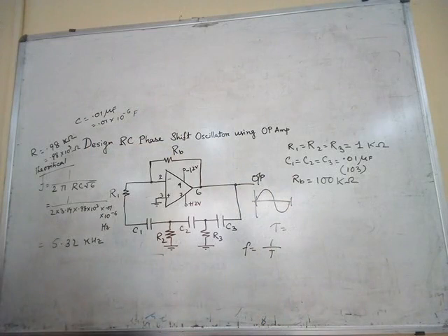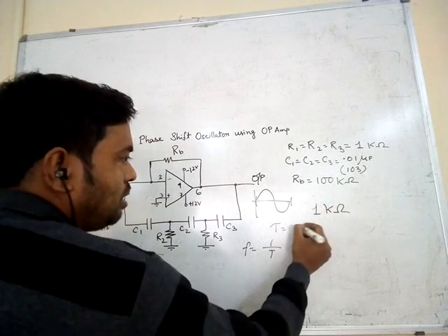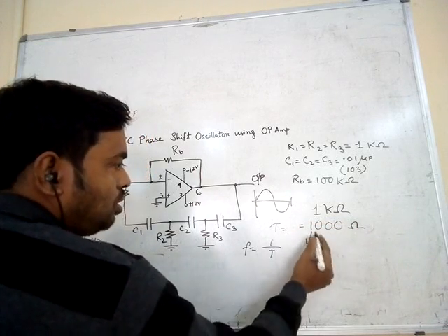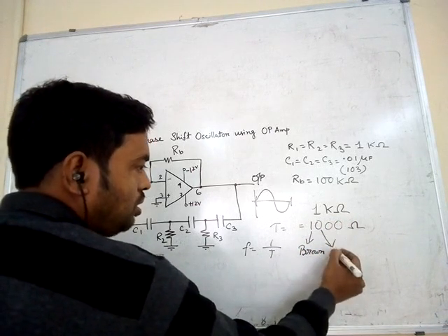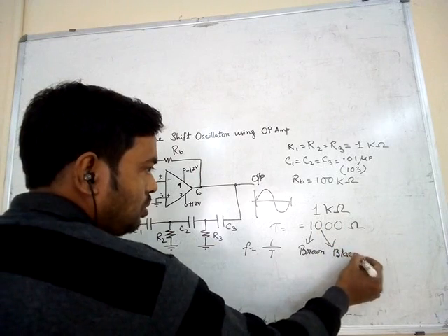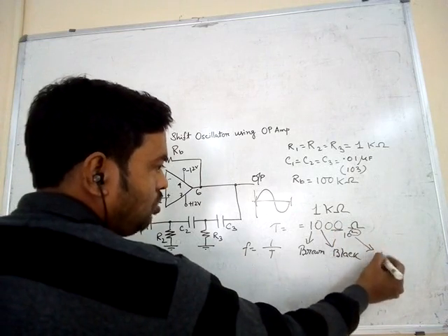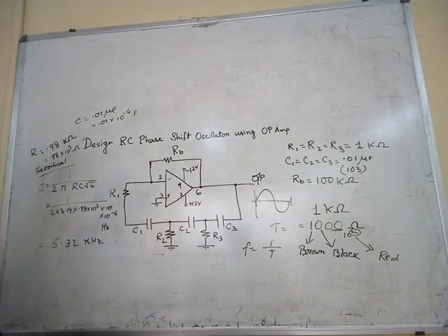Next we go for the resistor. The value of this resistor is 1K. How do we calculate the value from the color code? 1K, 1 kilo ohm, that means 1000 ohm. We know the first band, 1, means brown. The second band is 0, so this is black. And then 00, that is 10 to the power 2. The 2 means, we know, it is red. So for a 1K, 1 kilo ohm resistor, the color code will be brown, black, red. You can see.